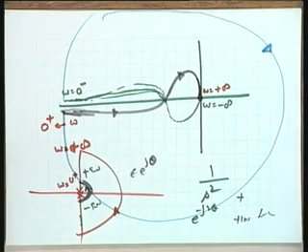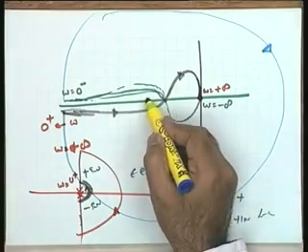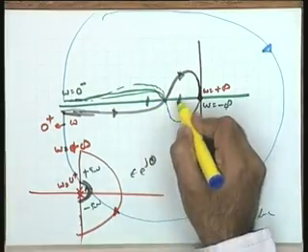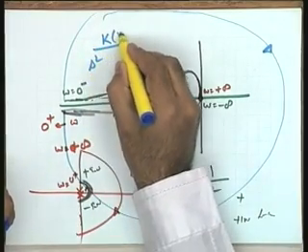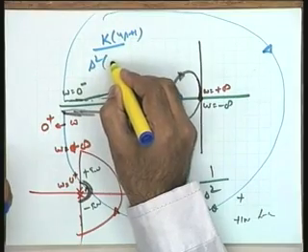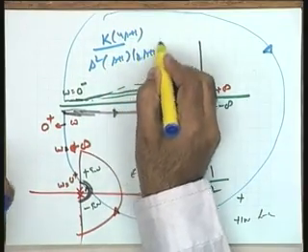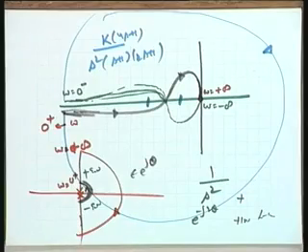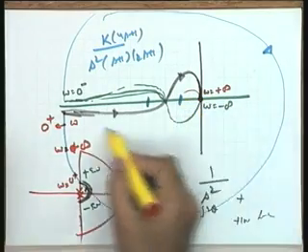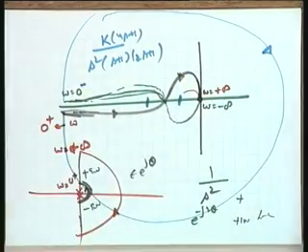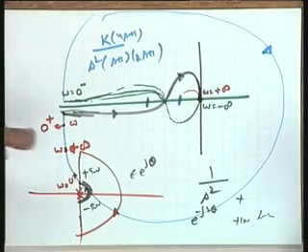Now you have to see. In this particular case, the numerical answer will come very clearly, because it will depend upon the magnitude, whether the point minus 1 lies here or here. And if I add k to the system, k(s squared)(4s plus 1) over (s plus 1)(2s plus 1), you can very easily see that by k the system can be destabilized or stabilized, because the plot can be contracted this way or expanded this way depending upon the value of k. K is going to change the magnitude.